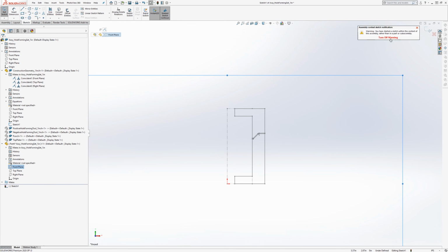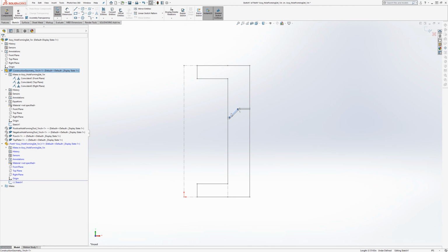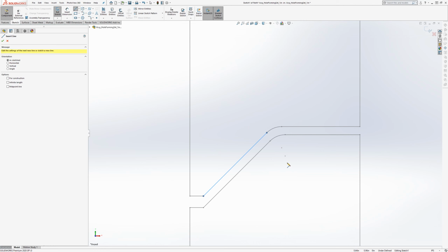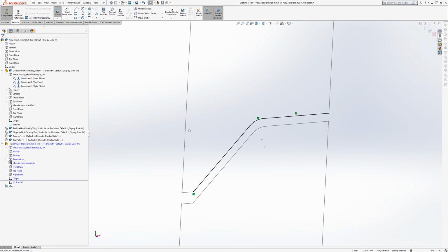Oh, so this is a good warning here that SOLIDWORKS provides, which is, I'm trying to edit this part here, but I've started a sketch at the assembly level on this part's plane. So it's giving you a warning that you're not actually editing this part. If you want to edit in context, you have to go to the assembly, edit the front plane, and then I can take geometry from there, so I can refer to it, let's say, with lines like that, or I can even project them in even though they're within the same plane. It's sort of like copying them in.